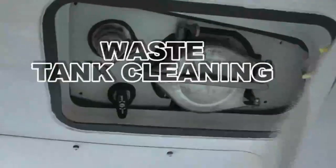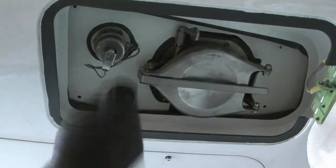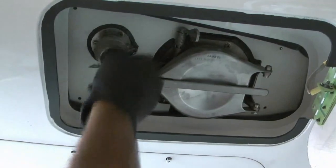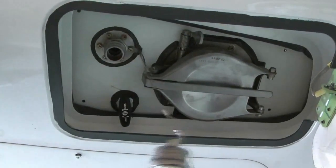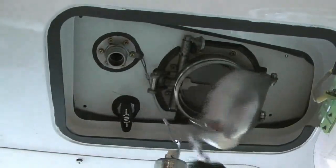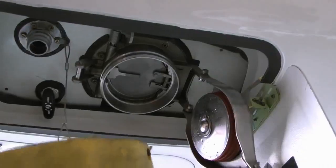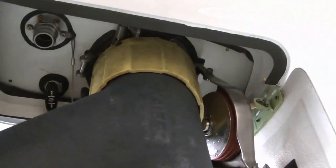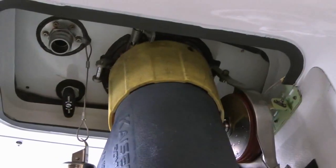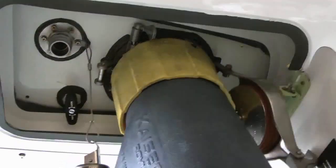Waste tank cleaning. Open the access door. Remove the rinse nipple cap from the RTS rinse valve. Release the handle of the RTS service panel drain valve cap and open it. Connect the lavatory dumping coupling of the lavatory servicing cart to the RTS servicing panel drain valve.